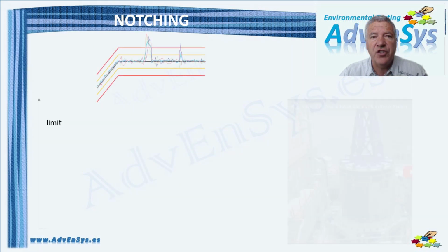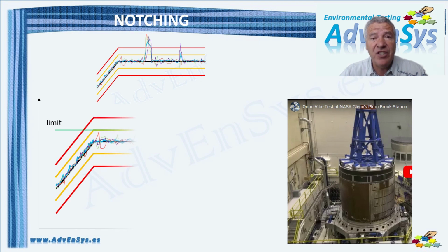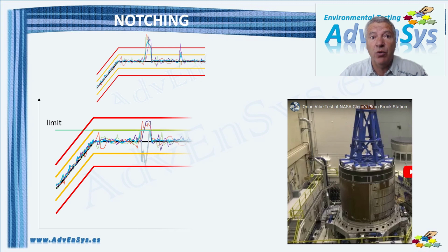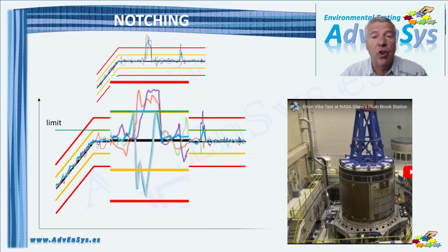If we would use a limiting channel on the fixture DUT fixing point for this task, instead of programming a level reduction manually, the limiting channel would try to keep the level below the limit, and therefore the control excitation would be automatically adjusted. Let's see the detail. Sometimes this technique is also called advanced notching.